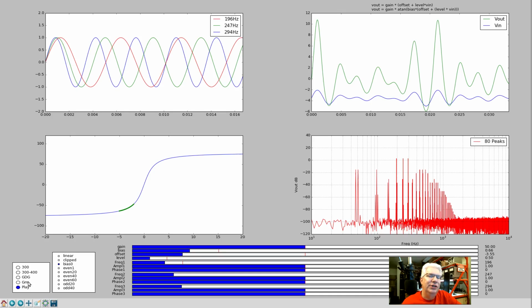But this answers your question about what is intermodulation distortion. How do you minimize it? If you're doing audio amplifiers, you want to, not necessarily stay in the middle of this waveform, which is where all the books say choose the middle, because you're going to get some symmetry there. If you move your bias point off the middle a little bit, you will reduce the odd order harmonics and promote secondary harmonics.